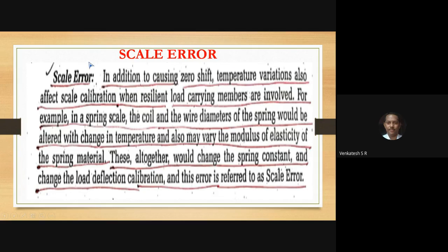Then the pressure of the air tank of the air compressor is 4, but the needle shows 4.1 or 3.9. That is called scale error. You need 4, but the dial pointer shows 3.9 or 4.01. That is the scale error.